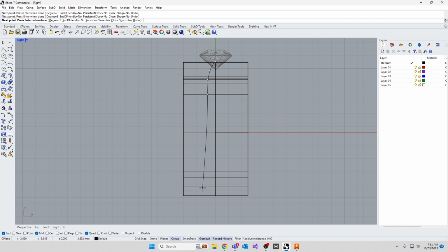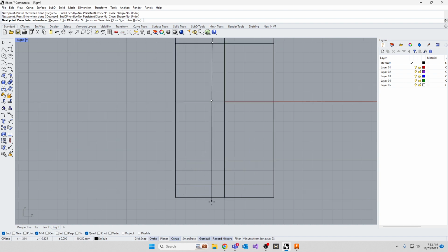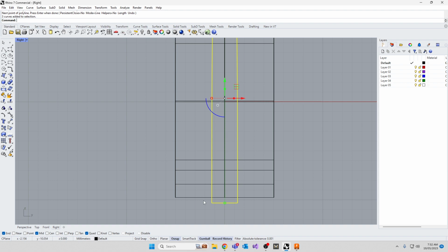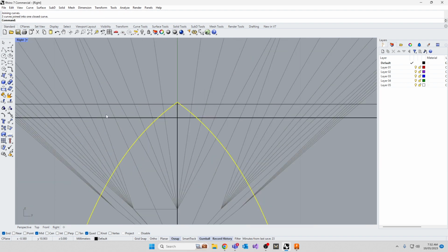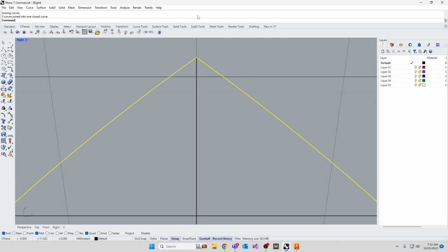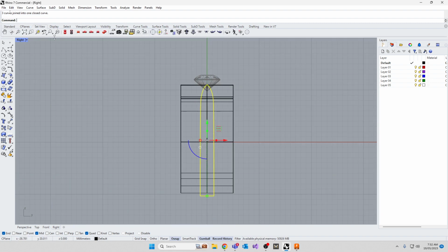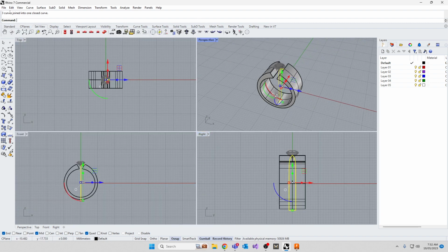And we want to basically come straight down, right? Something like this. So I'm going to take this one, mirror it over the other side, like that. Draw a line, joining it at the bottom. Join these two together. Okay. We hope it's touching up the top. It should be. Right, we're going to extrude this in the opposite direction.